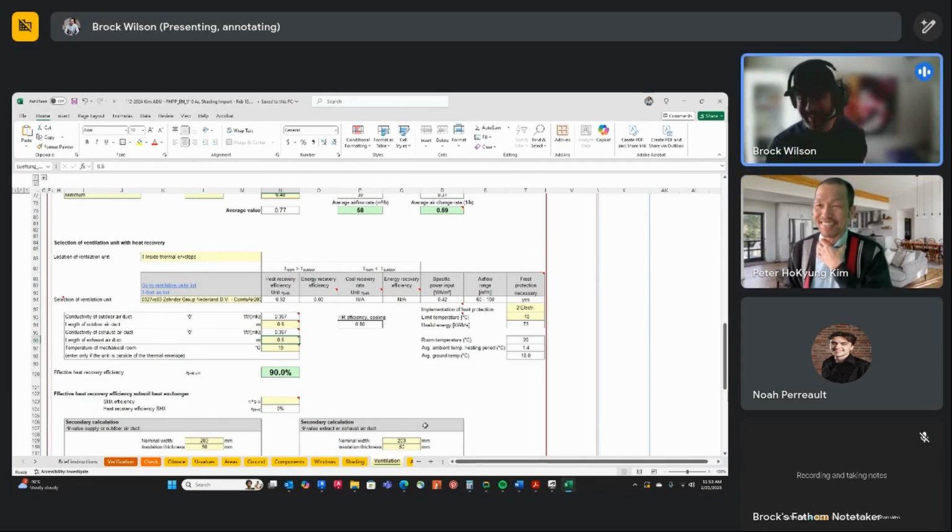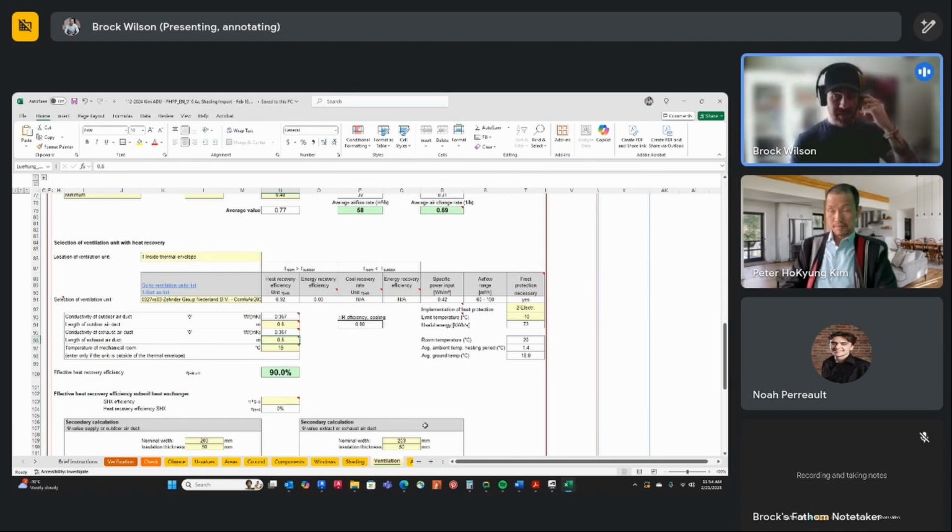For example, what kind of choices do I have? Well, good question. You don't have very much real estate. Our thoughts at first were that little closet at the entryway, but that's going to take up a lot of room for clothes and whatnot. I would probably suggest maybe your bedroom closet, locating a little bit of a closet for the ERV. The clothes closet could be the entire length, but that's quite large in any case. The reason is that we can then have the exhaust and intake lines directly to the outside wall.